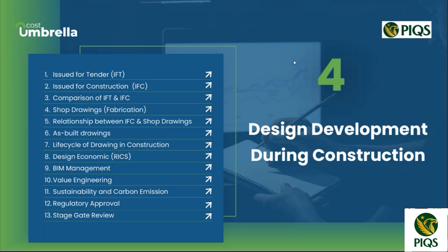But the best practice is that if the IFT package was issued and the contractor had highlighted some points from the constructability point of view, it is better to incorporate these points during the bidding stage. Otherwise, it will lead to variation orders and then to disputes. Thank you.